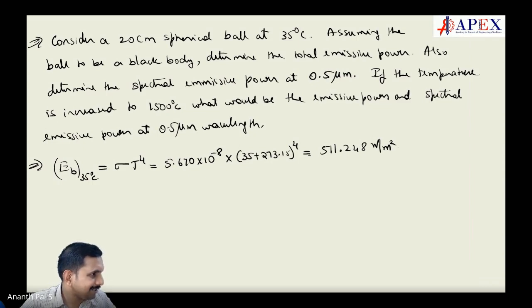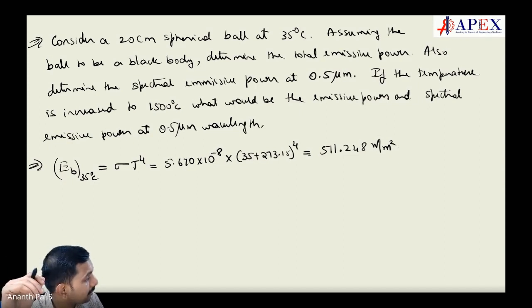So if you were at 35 degrees centigrade, you are actually emitting more than 5 light bulbs of 500-watt bulb of energy continuously. Take 0.7 as the emissivity. It is in that range only. It's not very less. If not 500, it's 400. That's it.